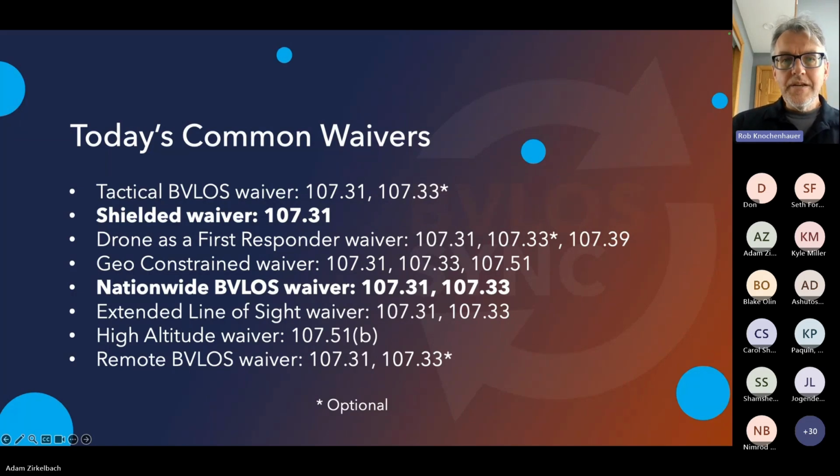So there are DFR programs that are run, not necessarily, most of them are actually not run under Part 107, but these are the rules that they would be granted if they were operating under 107, which is BVLOS. You would have, in some cases, visual observers associated with those operations, in some cases not, depending on what they have in place for understanding of their airspace. Some of the DFR programs are leveraging ground-based sensors for airspace awareness.